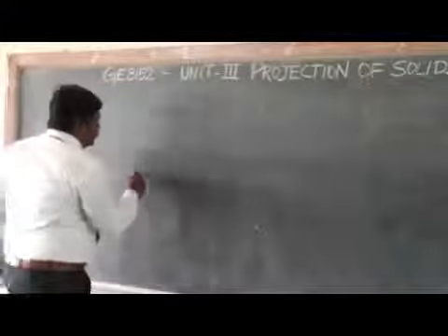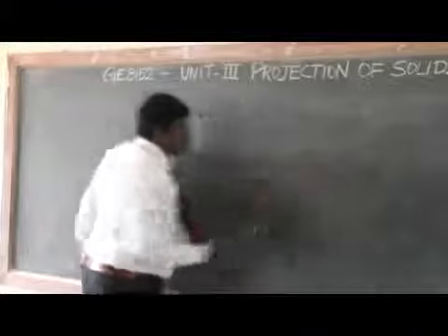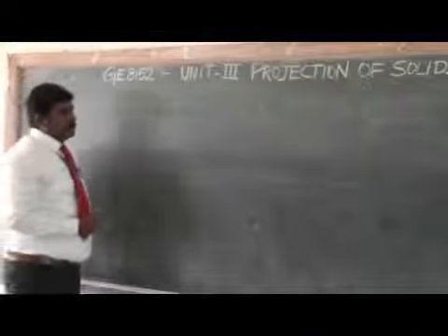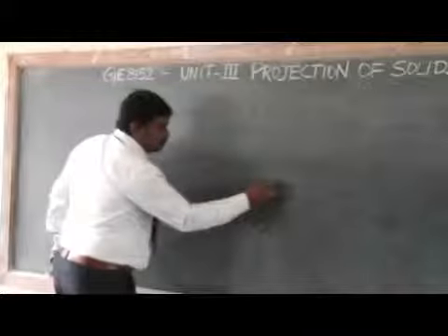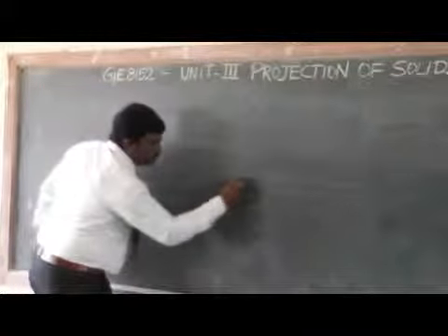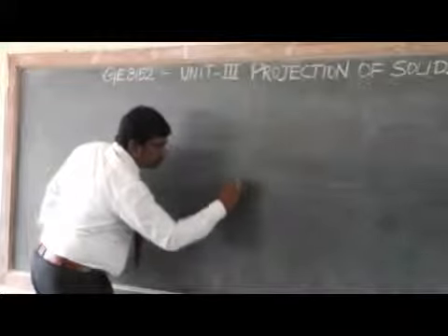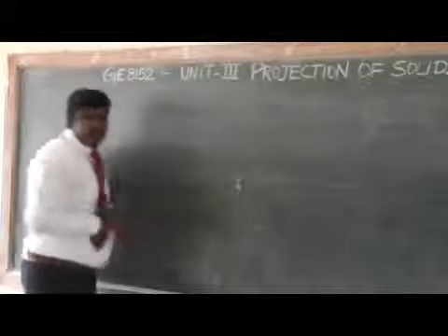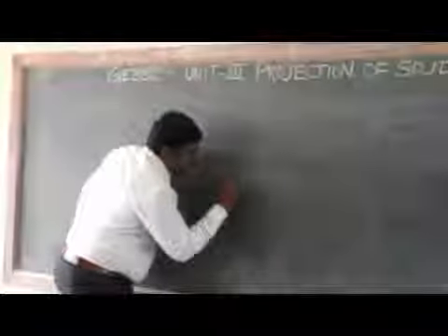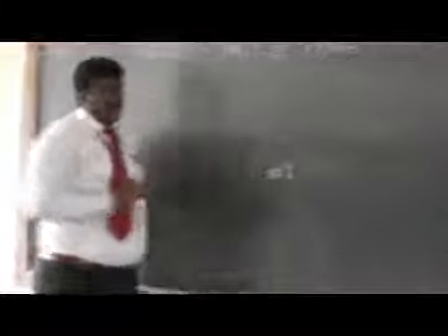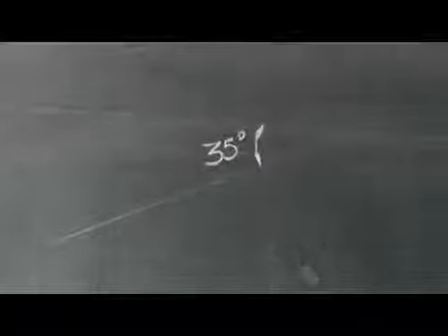So let us draw the reference line. Draw another line using H pencil at an angle of 35 degree, where one of the base edges is going to rest.